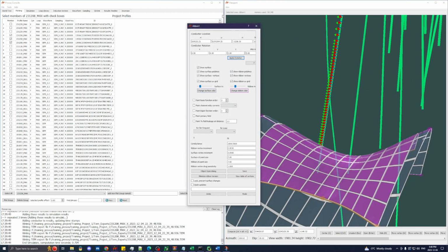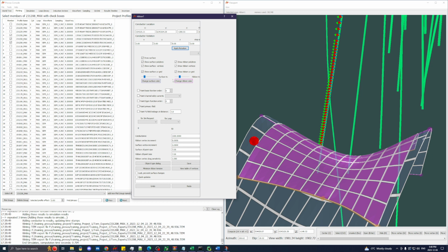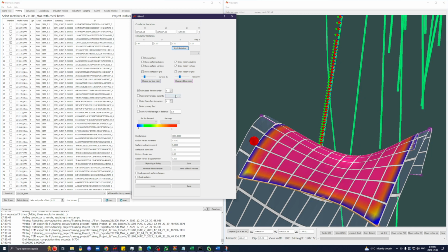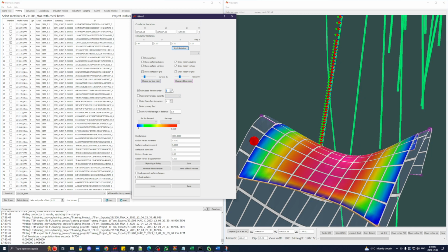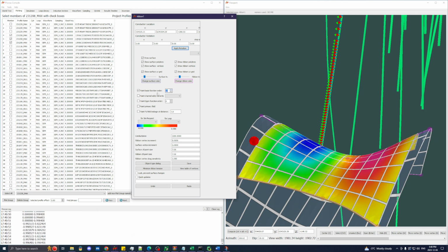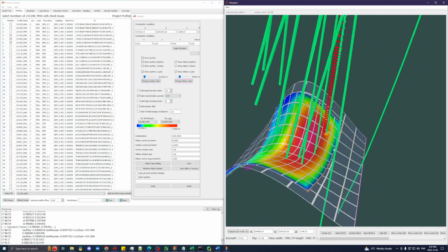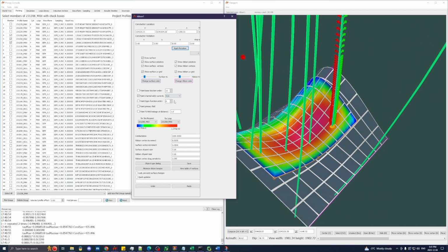But now that we've run a simulation, we can go back to our ribbon conductor, and if we press enter, bring up the object dialog again. And now we can get into these variables that I sort of skipped over. If I click this checkbox here, it will paint the basis functions on our ribbon conductor, which can be very useful. It can also paint the eddy currents. Our data here is UTEM, so channel 1's the latest here. So we can go to the earliest time here and see what the eddy currents are doing and watch it sort of disperse.